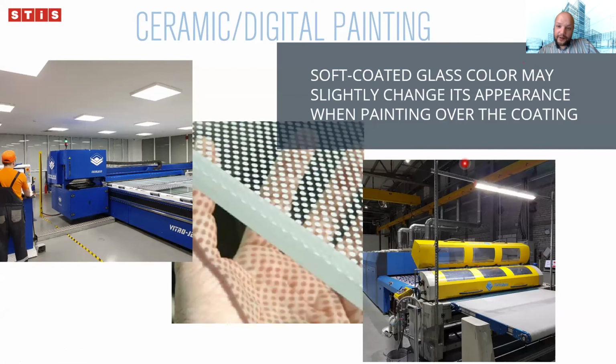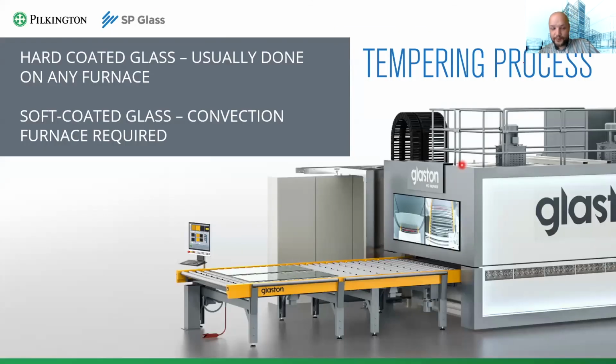Now, what I forgot to mention in the tempering section is that the hard coating shines when you are talking about bending. When you have a standard bending, your coating has to be positioned on the inner side of the bent glass.